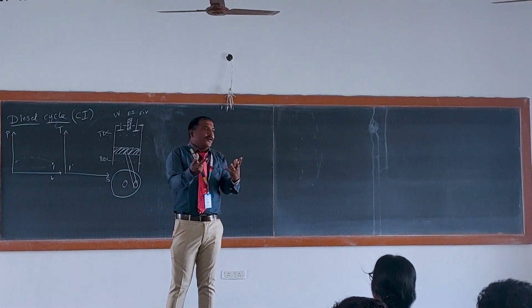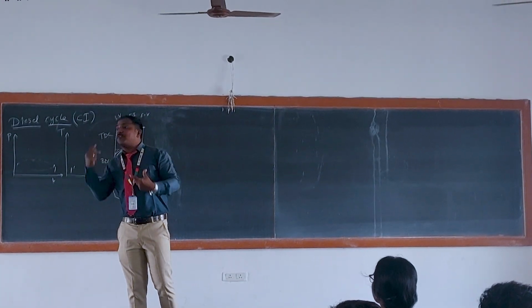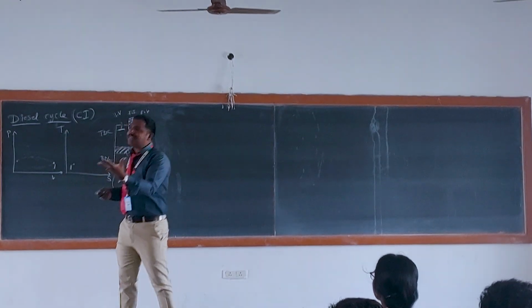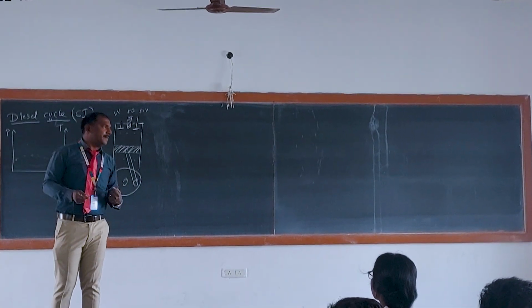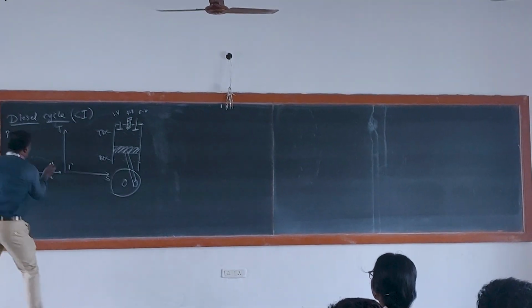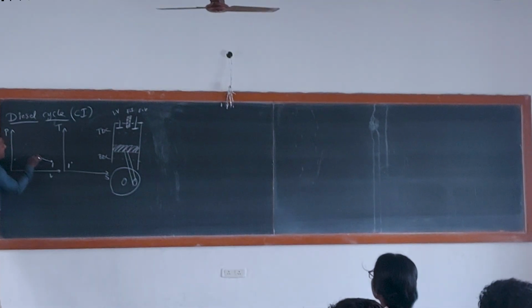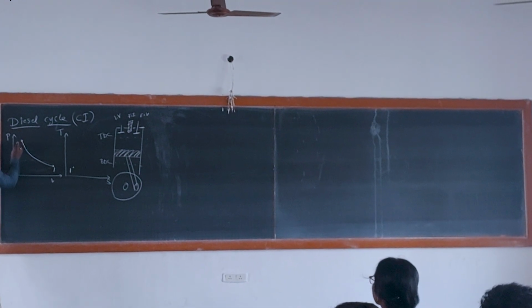When it increases above the self-ignition temperature, the combustion takes place. Because we need blast, right? We need blast inside the cylinder to extract the work. Clear? So this process continues till the piston reaches to where? BDC. So this is my 2.